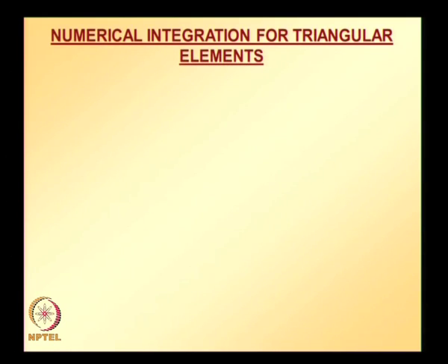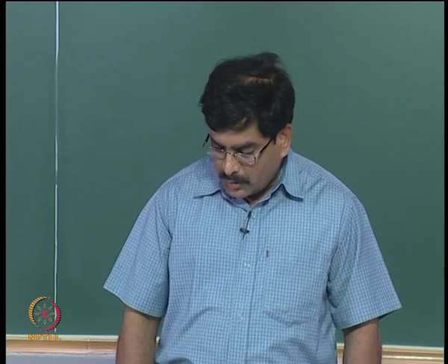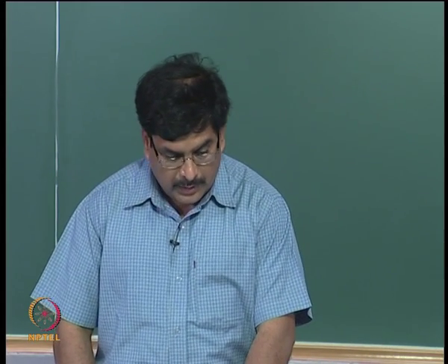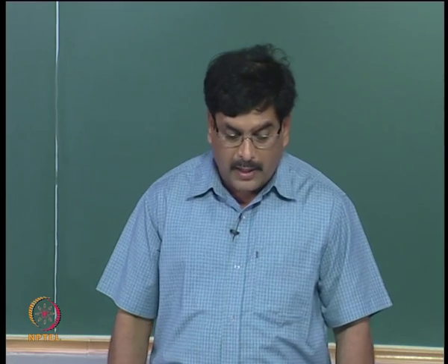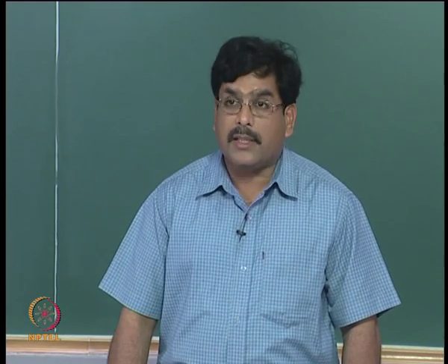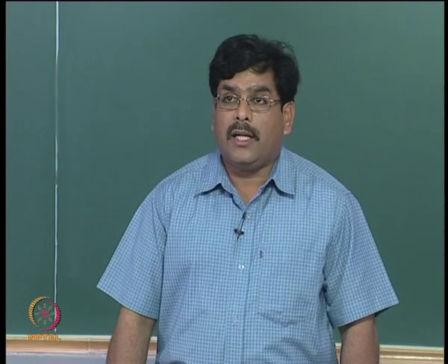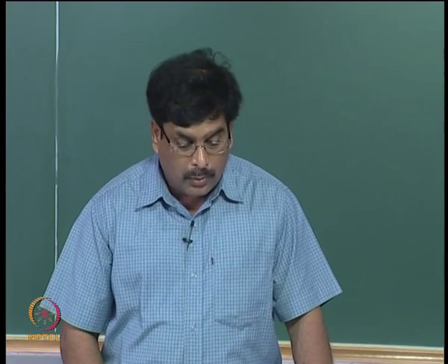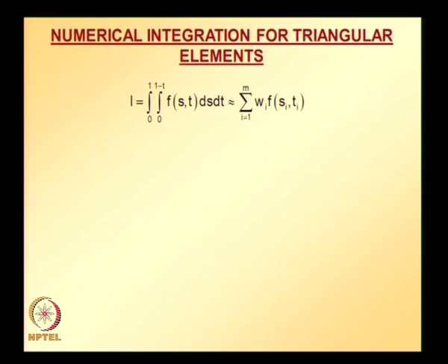So now let us look at integration for triangular elements. This integration for rectangular elements and integration for triangular elements, these details are very important for finite element equation assembly or finite element equation evaluation. So integration over a triangular area is nothing but this kind of integral, between the limits 0 to 1 minus t along the s direction, and between the limits 0 to 1 along the t direction.